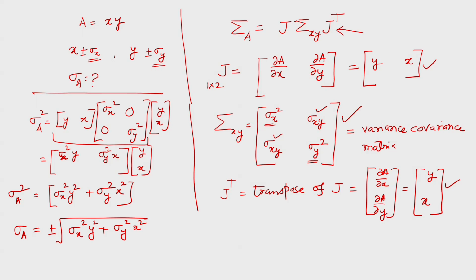So, now what I am doing here, I am trying to estimate the error that will be propagated to the area A if I measure x and y in the field. Again, I am assuming sigma x and sigma y, and I am trying to find out what could be the error propagated to the area A with these assumed values, and there is a reason to assume it. In fact, I should do, let us say, 100 measurements of length and 100 measurements of width. What is the characteristic of the error of these measurements, and if only random errors are present, what values are possible for sigma x and sigma y.